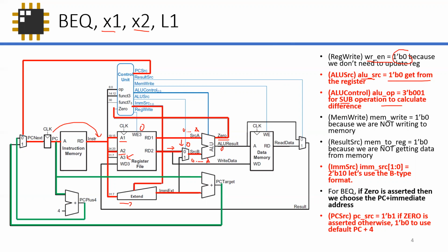Or if you remember, like last time, one of the specifications that was mentioned for the ALU is that a zero bit must occur if all the bits of the ALU result are 0, right? And then that zero bit is sent back to the control unit. Okay? So the reason why we use subtraction is to compare whether the result is 0 or not. If the result is either positive or negative, as long as it's not 0, then the zero bit will never be set. Okay? So that's the control signal that tells us whether my branch is taken or not.